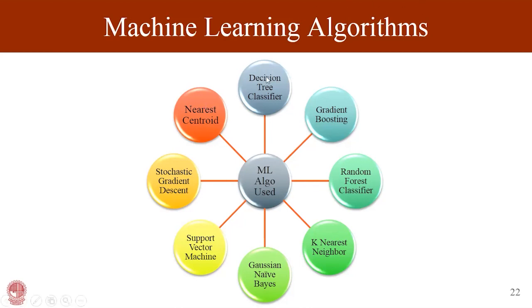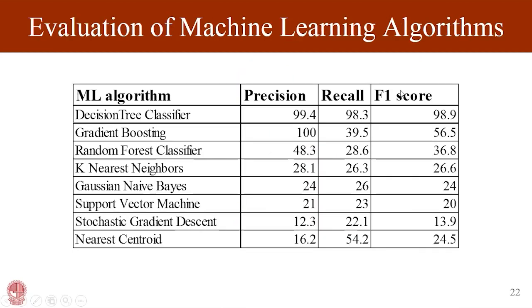Now, here are the 8 algorithms that we used in our machine learning application. Firstly, as an input, we use the acceleration on three different axes, the X, Y, Z axis, and as an output, we use the type of fault that is occurring in the machine. And then we trained our 8 different algorithms. After training these algorithms, we evaluated the trained models using tenfold cross validation.